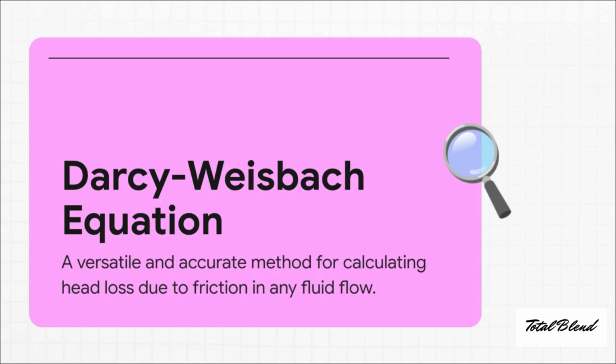And fighting out of the other corner, we've got the Darcy-Weisbach equation. Look, if Hazen-Williams is the seasoned veteran, Darcy-Weisbach is the younger, more versatile, technically brilliant champion. This one is built on solid scientific theory, not just observation. And that makes it way more powerful. It can calculate head loss for any fluid you can think of, not just water.